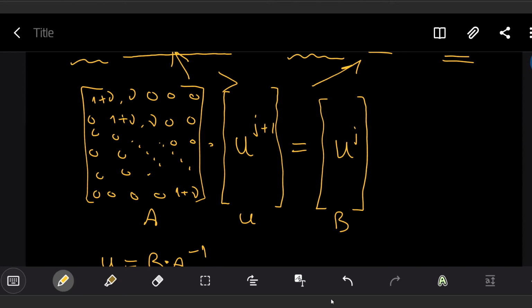Depending on the method, it can be a 2-diagonal, 3-diagonal, or 4-diagonal matrix. It depends on which button you click and which method you choose inside the solver. And this is how the Courant number enters the solution. It's actually a bit opposite from what you have been asked: by increasing the Courant number, we increase the velocity of the solution, but we decrease the stability.